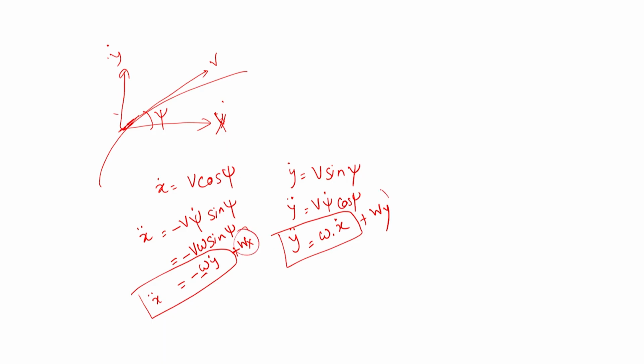So, I gave some white noise, omega x and omega y, just to model if I miss something. If it is not a proper coordinate turn model, then I am missing something, because the truth could be anything. I am enforcing this kinematics here, but it may not follow the kinematics. That uncertainty, that ignorance, is modeled using omega x, omega y.